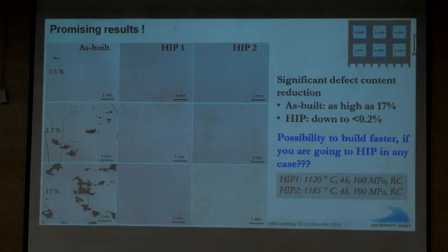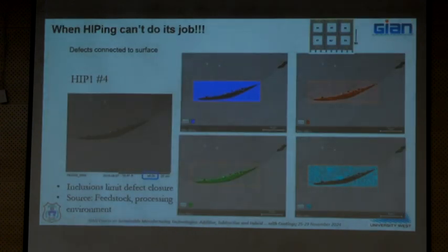How many of you have heard of thermally induced porosity? You have heard of thermally induced porosity. So, that can happen. It can look like a nice microstructure, but when you expose it to temperature, it can open up again and give you porosity. But we tried it in that case and it didn't happen.